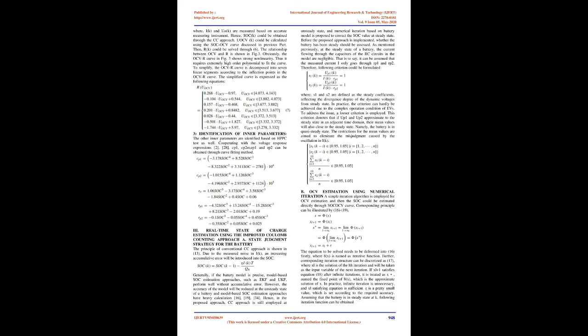B. Offline parameters identification to verify the performance of the proposed algorithm. An 18650 Li-ion battery with the nominal capacity of 3 Ah and rated voltage of 3.6 V was modeled. The parameter identification tests were performed on a REC 8511 programmable electronic load, where the measuring accuracy of voltage and current is 0.03% and 0.05%. Then, the data were processed in MATLAB.